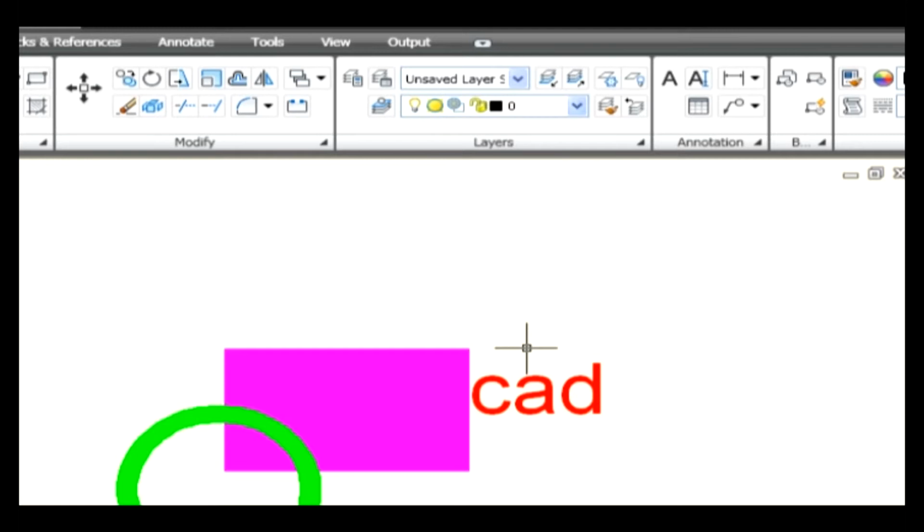Let's see the third option, which is Bring above objects. This option helps to move the selected objects above the specified reference objects. Let's create a sketch on the drawing area and select the Bring above objects option. Now the command line asks to select objects. Select the first object, which is drawn and overlapped by other objects, and press Enter. Now the command line asks to select the reference objects. Thus, select the required object on which the selected object is to be placed over and press Enter. Thus the object has been brought above the referenced object.